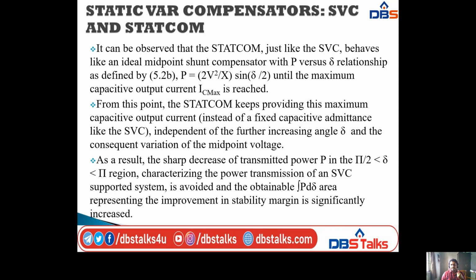From that section I am taking the equation P equal to 2 into V squared by X into sin delta by 2. This holds until the maximum capacitor output current, I_C maximum, is reached.